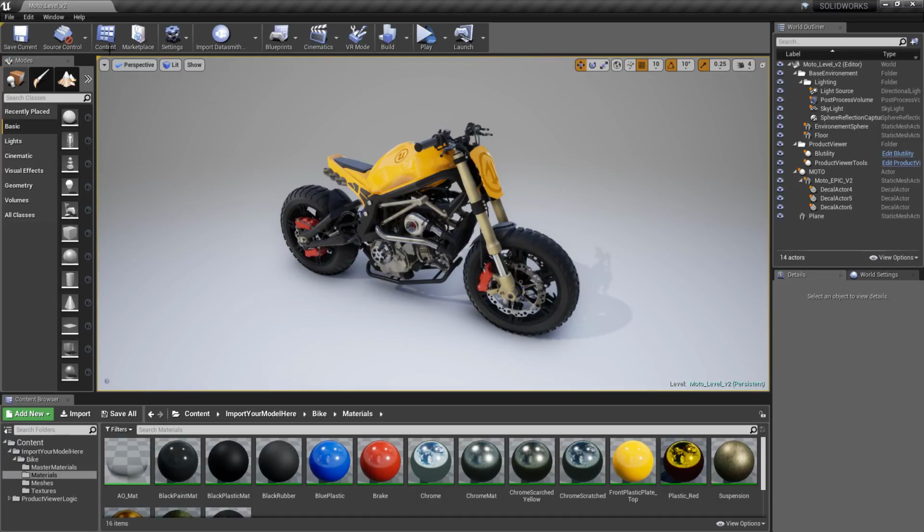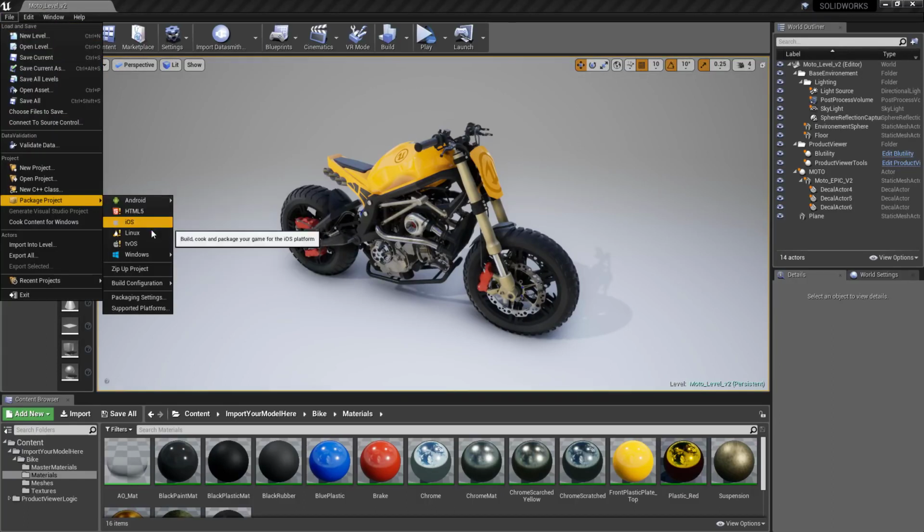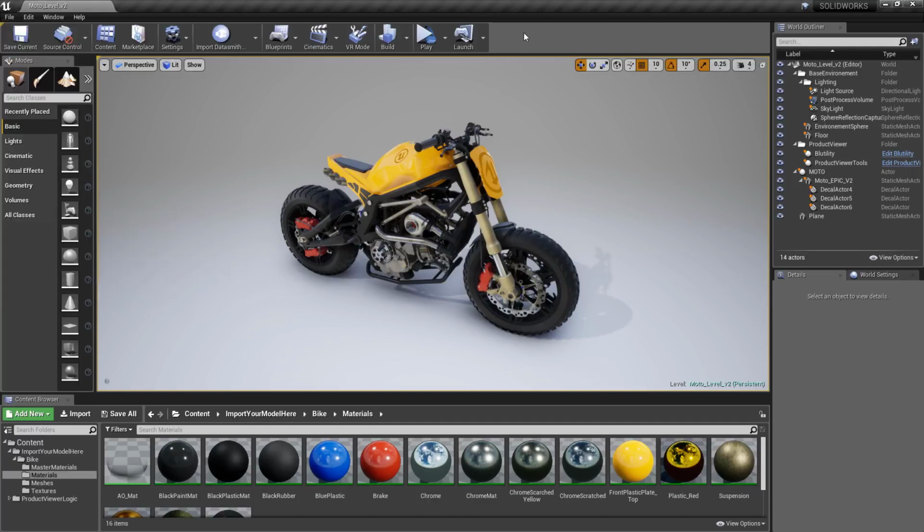Very simply, like I've just shown there, we would simply go to File, Package Project, and you would select where you want this to go. If you're going to something like a Mac format or a different format, you can simply do that. In this case, I just went to Windows 64-bit, and it's a shareable standalone application that launches as its own VR app. This is an excellent way to experience that data or share your experience of your CAD design with anyone at that point.